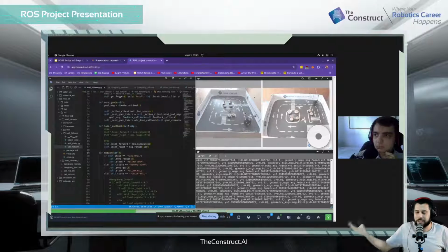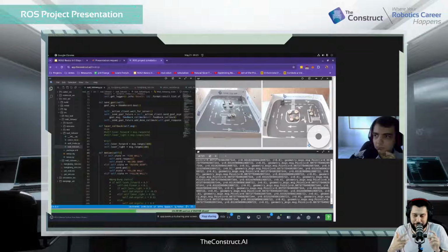So instead of looking at only the right side, you're looking a little bit above and a little bit below. Your set point is the difference of those being zero, which means the triangle between the robot and the wall has to be sort of equilateral. That's another way to do it on two spots.